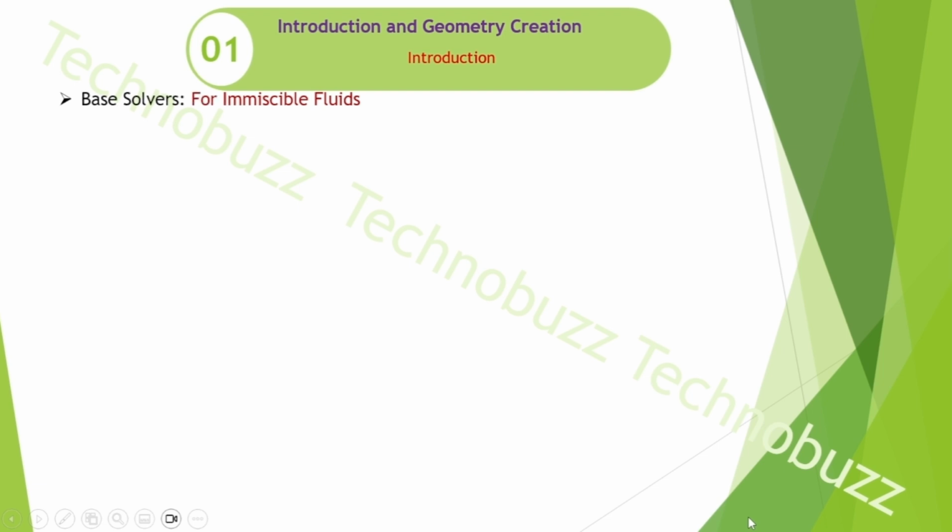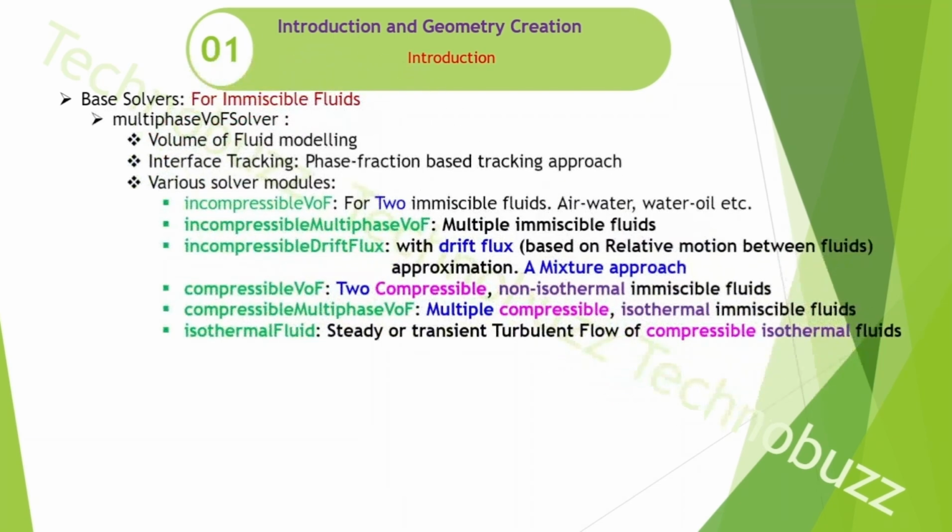Let us explore the multiphase modules in OpenFOAM 12. Multiphase VOF solver. Different variants of VOF solvers are listed here. Both incompressible and compressible versions are available to cater the needs of various applications. These versions can model thermal hydraulics with turbulence in steady and transient mode.